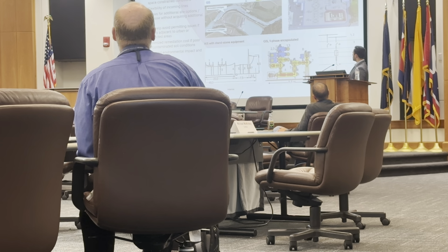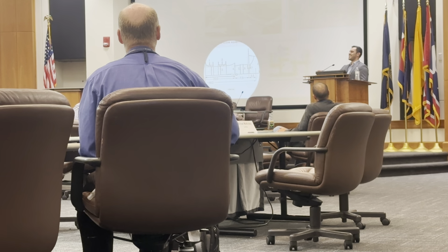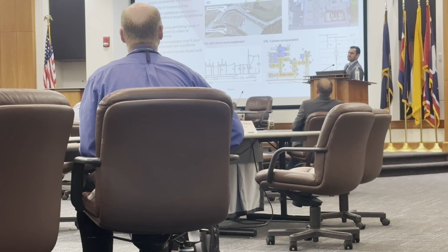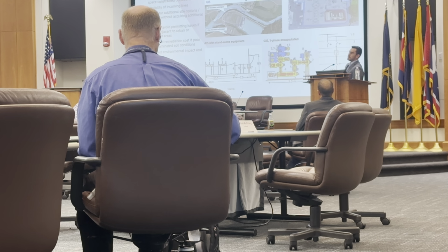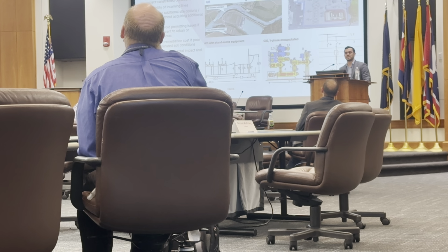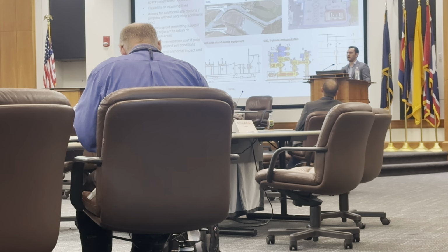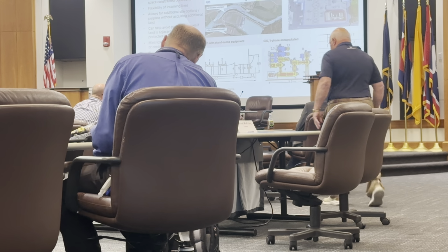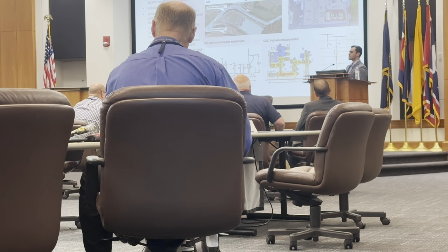So here I put a quick little example. Let's see if I can get this to work. AIS, typically 48 meters from side to side, and the GIS, you're looking at 5.5 meters for an entire substation. Recently I did a substation building design where a 230 kV was able to fit in 270 by 38 feet. Right? If that were to be an AIS substation, I can tell you that it's going to be 80 times the size.